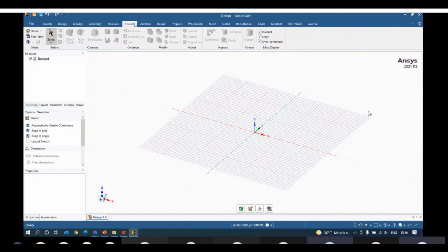There first you'll perform structural analysis, then you will get the stress concentrated region, and you'll take that STL file for design optimization into SpaceClaim, and you have to give some smoothing to that geometry, right? So there you can use Facets to work on it.